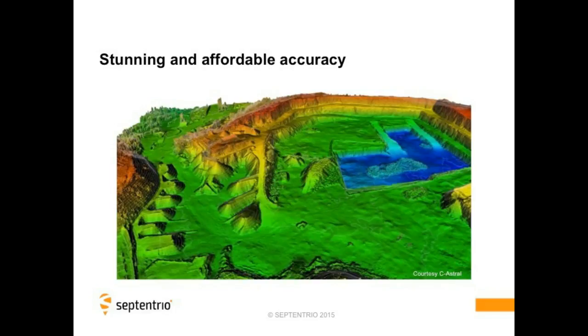An interesting additional aspect with using high precision GPS on the UAV for mapping or for georeferencing the images is that it also aids the stitching process in situations like this one, where some areas of the pictures may have few distinguishing features or a lot of image noise.